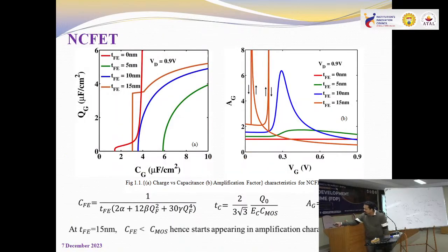This is what is happening here. When these two are close to each other, you are getting maximum, and you cannot increase the thickness randomly. If I have to improve the performance, you cannot say I'll put 100 nanometer. There is some limitation, because if you go beyond that, hysteresis appears in your device. Although if you are going for a memory application, you can obviously exceed the thickness beyond the critical thickness. For digital application, it should be well within TC.